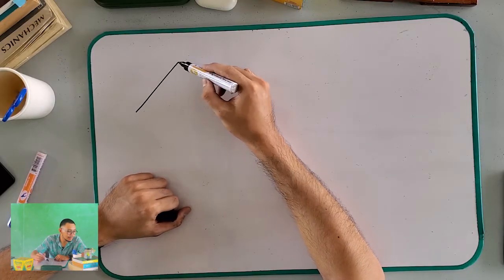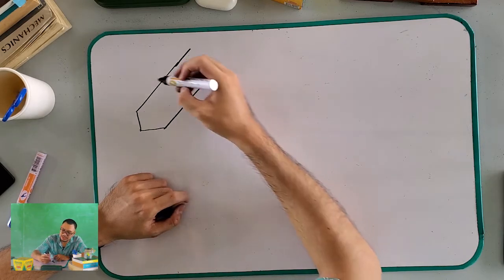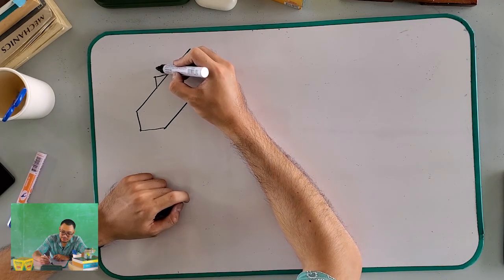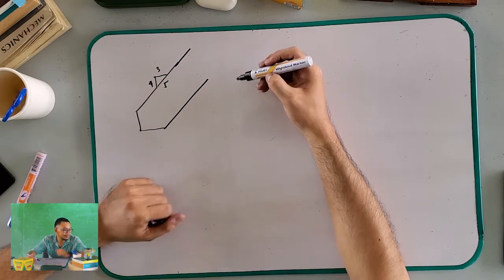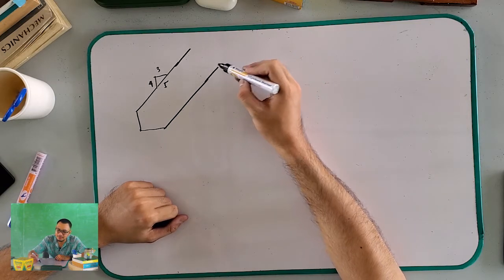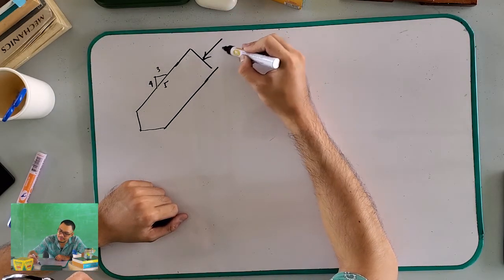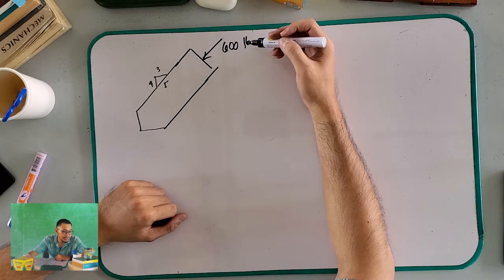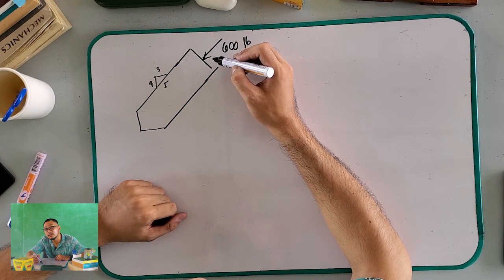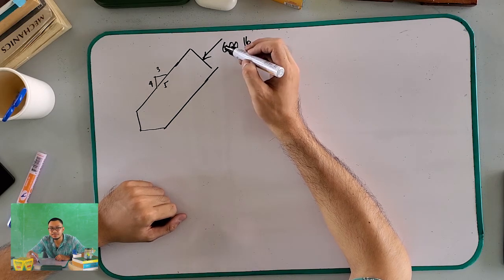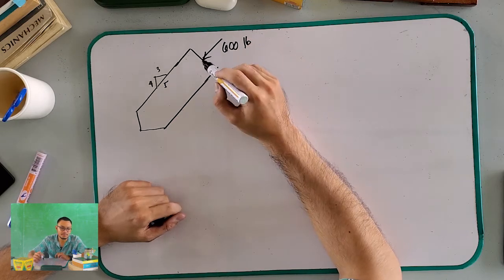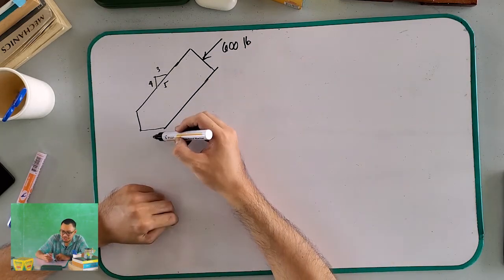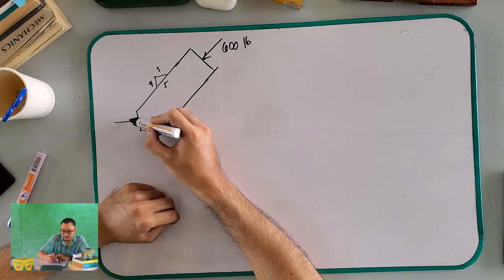First is to draw the free body diagram. Where do we draw it? On our inclined member. Your inclined member has an angle with the 3, 4, 5 triangle. And then a 600 pound force is applied to our inclined member. So there are reactions here and here.